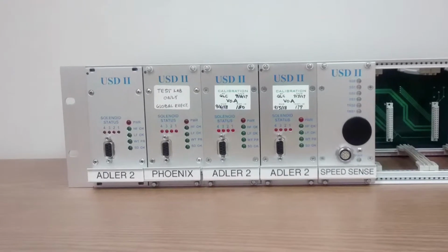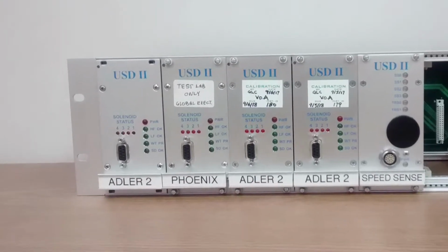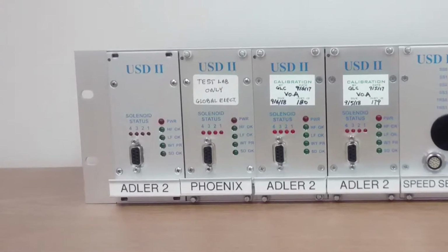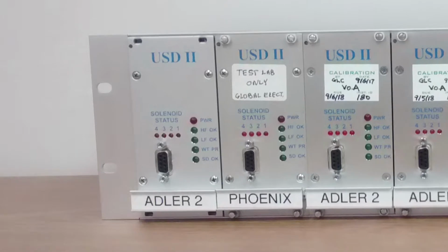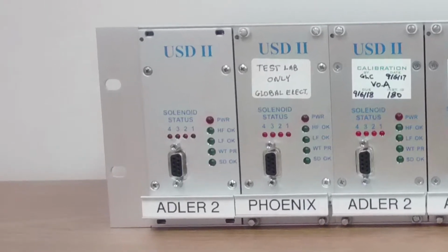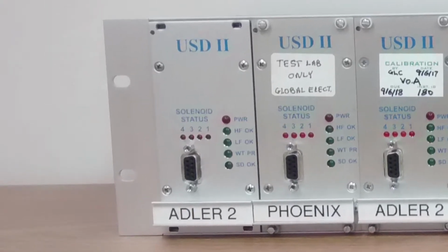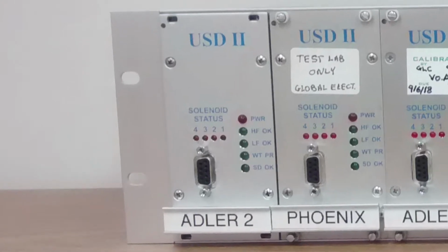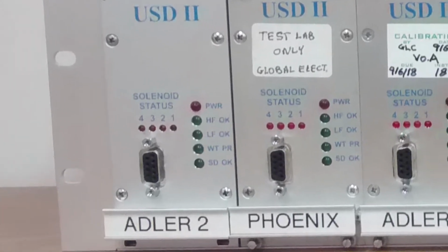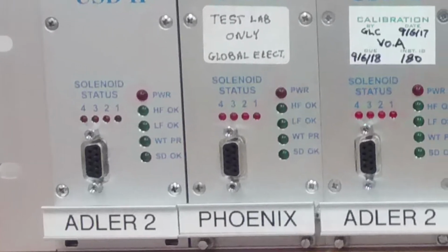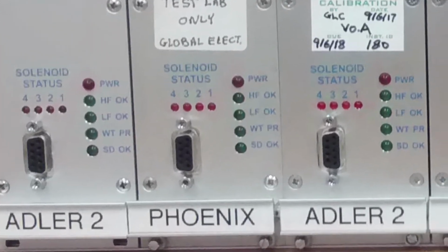The USD-II, as it is called, consists of a 19-inch wide chassis with a backplane motherboard designed to accept 7 plug-in modules. Several different types of modules are available for use in the rack, depending on the particular application. In many cases, users choose a module that matches the electronics found within their company's own transmission control unit, so that test hardware duplicates the relevant portion of the automobile's electronics.